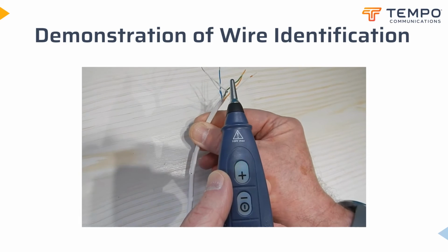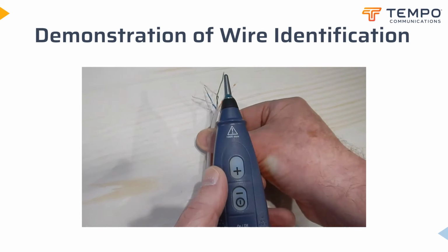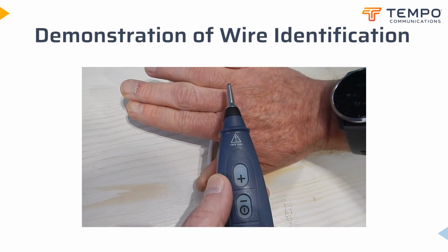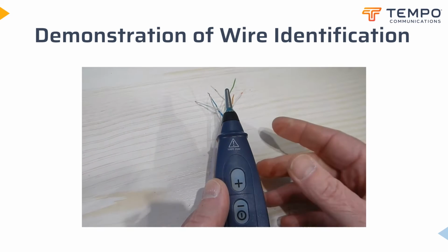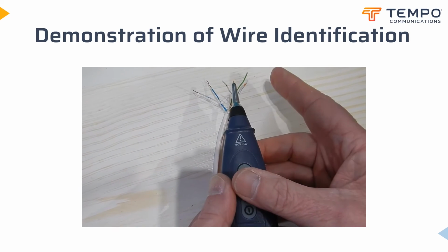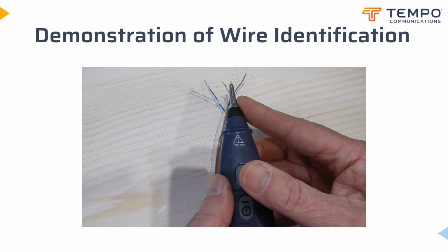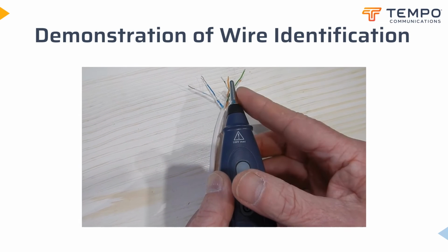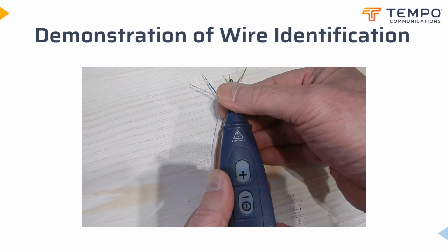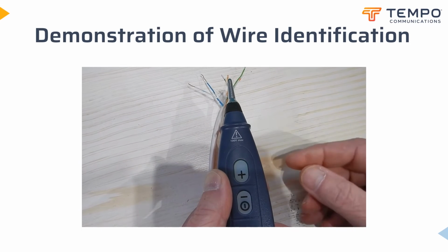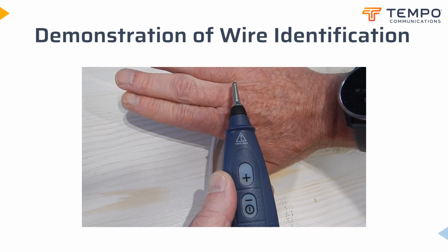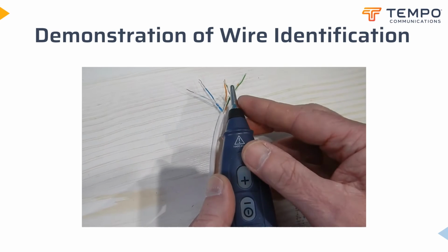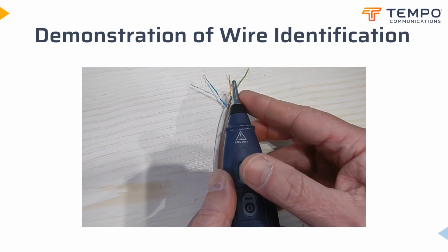But this is the pair with the signal on. And again, if you get your hand in the way, it shields it. If you touch the tip, it attenuates it. So these are things to avoid. Beware of the shield, and be aware of where you're grounding.